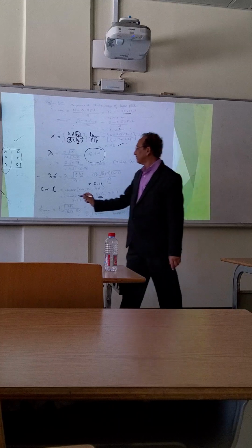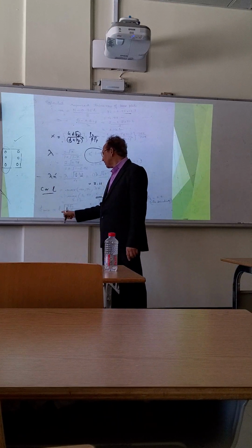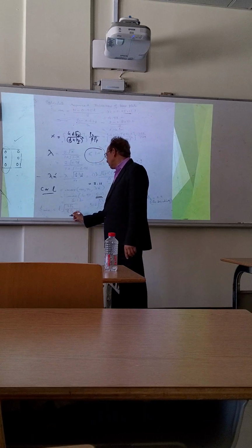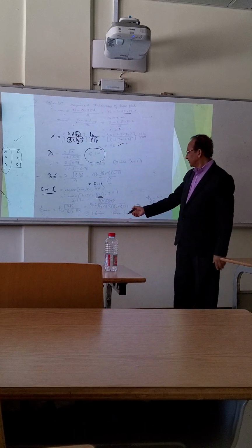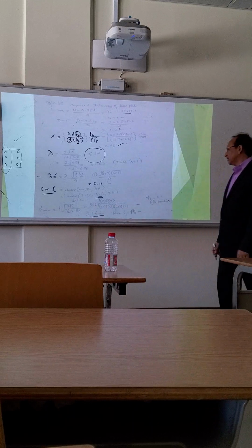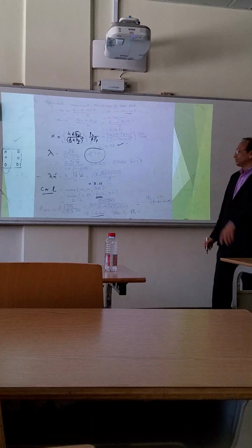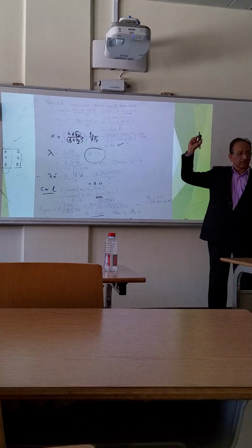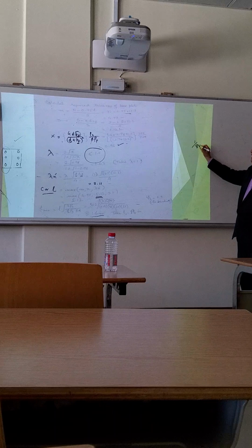So we take this maximum value 5.12, and then t minimum required is l into square root of 2 Pu upon phi Fy B N. All these values are available. You substitute and you get this value as 1.6. You will not take 1.6, but you will take the value according to the thickness available in the market, every 1 by 8 inch.